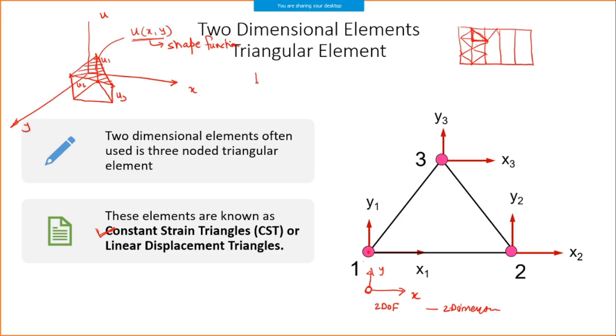If I consider an element, u is a function of x and y, I can have a single linear element, u = a0 + a1x + a2y. x and y are the two variations. The power of x is 1 and y is 1. That's what is called linear.